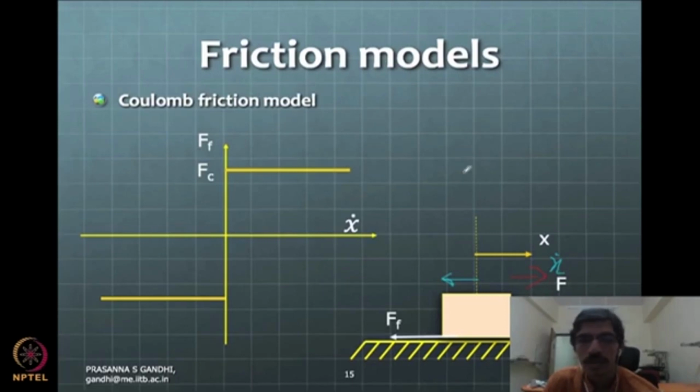And for the magnitude of friction, for simplicity, when you have this mu N kind of way of representing the system, typically you say the friction force here is mu times N. That is mu times N only after the block starts moving. Before the block starts moving, friction is equal to this F force. We can see whether that can also be captured in the model. So think about the way we can now write the equation for Ff, the friction force here.